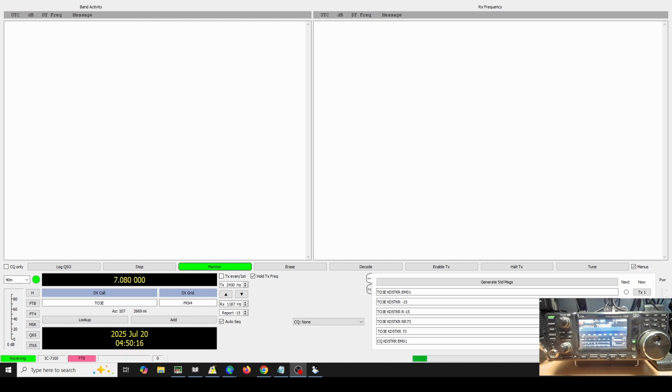Wanted to talk a little bit about how we set up for running digital modes, more specifically FT4 and FT8. So the configuration that I have here at the house is, of course, I have my USB cable between the transceiver and the computer. Before I hooked that up, I installed the ICOM USB driver and verified that communication. There is some configuration that needs to be done in the radio. I'll cover that in just a minute after I talk about applications.